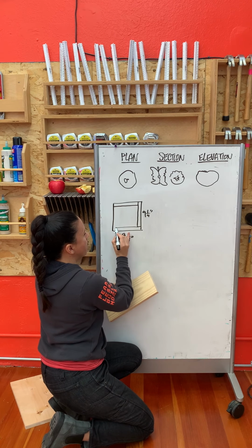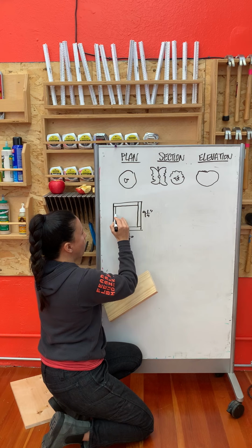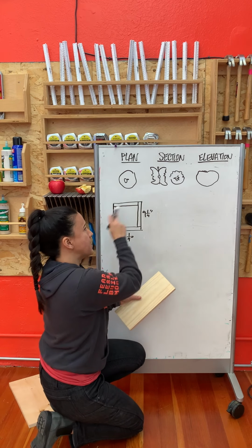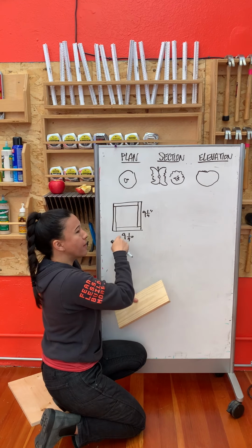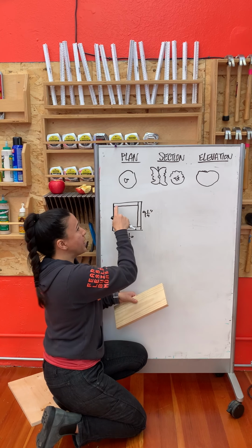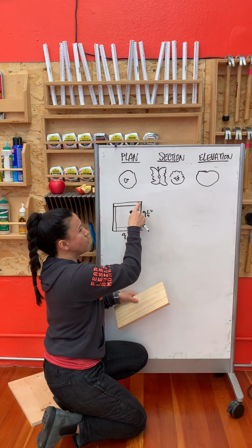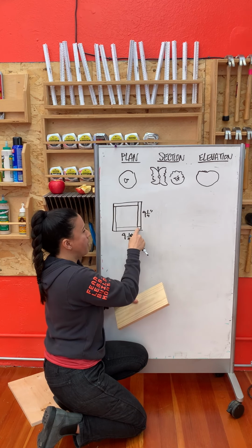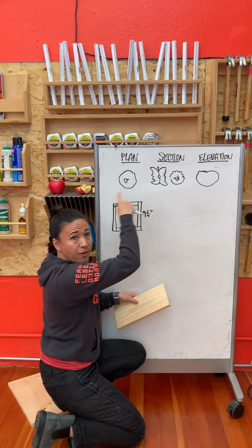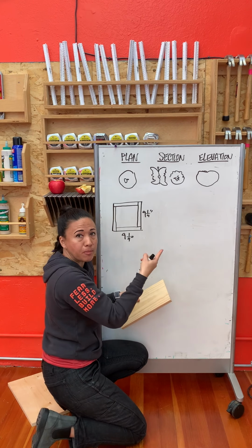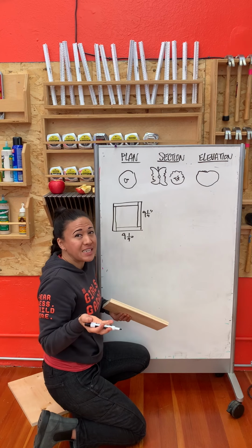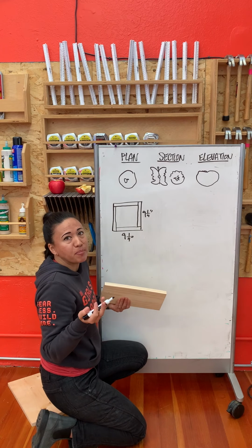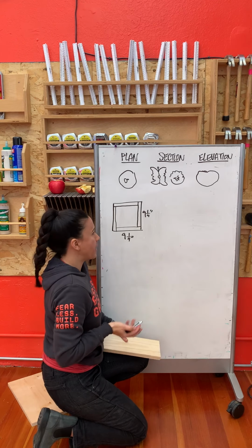Stop, wall, stop, wall. So what I did there, the way that the corners meet, that's called pinwheeling, where each wall butts into the next one. This one butts into this one butts into this one, etc. It sort of goes around in a pinwheel motion. I just think that's kind of a fun detail. It's just a fun building challenge, so I decided to throw that in.